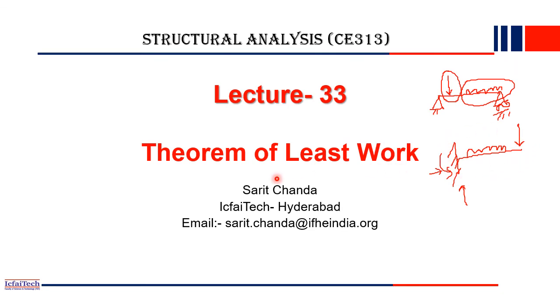So today we will discuss how to solve an indeterminate structure and how to get the reaction forces. For example, if I draw a simply supported beam with one end a hinge and this end also a hinge, then here you have two unknown reactions, one vertical and one horizontal. Similarly, here also we have one vertical and one horizontal. So in total we have four unknown reactions: 1, 2, 3, and 4.